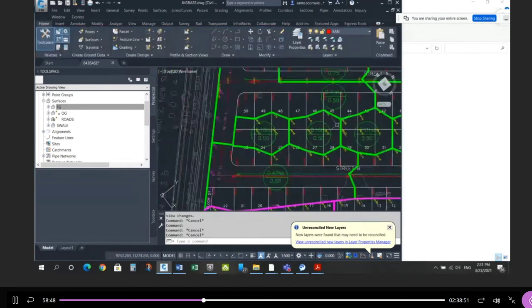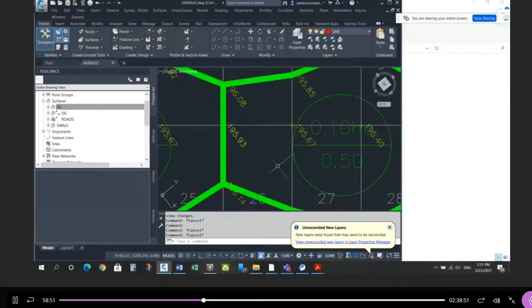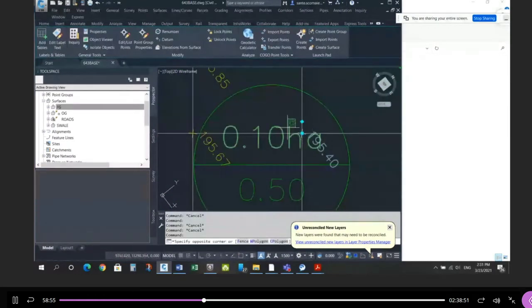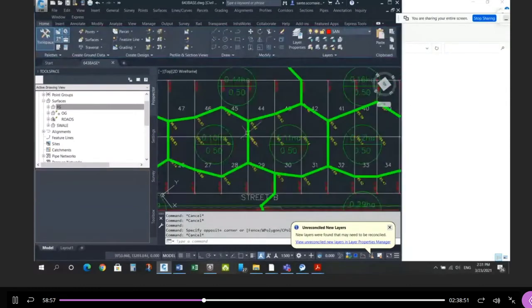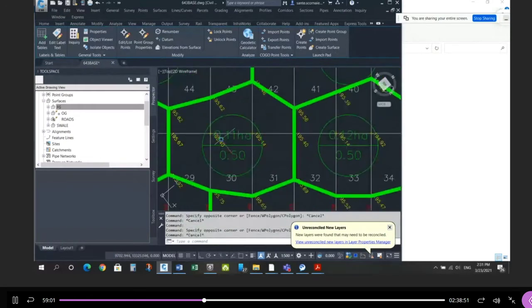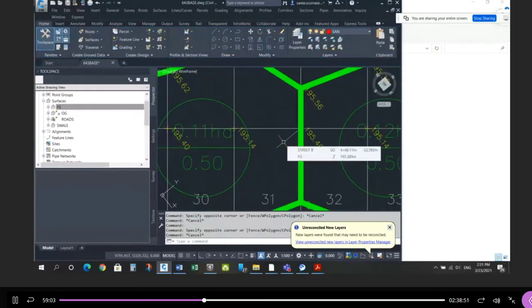And I would do that throughout. So if we look at the next one, the low point is here. So I would put the catch basin right here. If I look at the next one, the low point is here, I would put the catch basin right here, and so on. Always catch the flow before it crosses the property line one last time, and take the majority of the flow and catch it before it crosses a property line one last time.